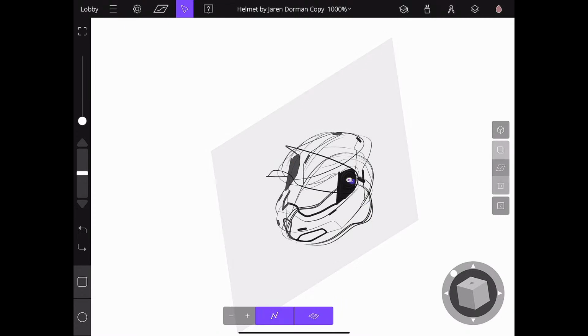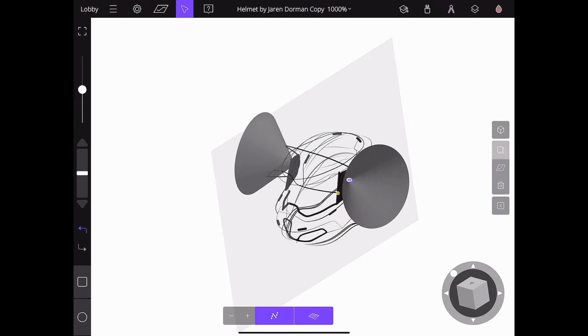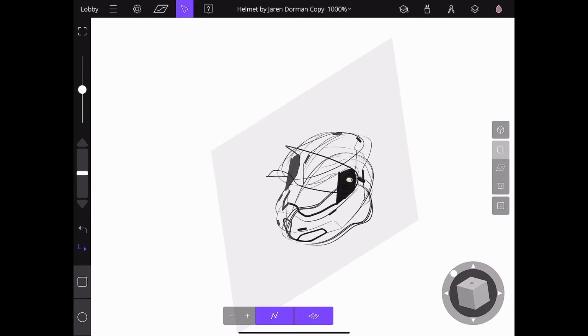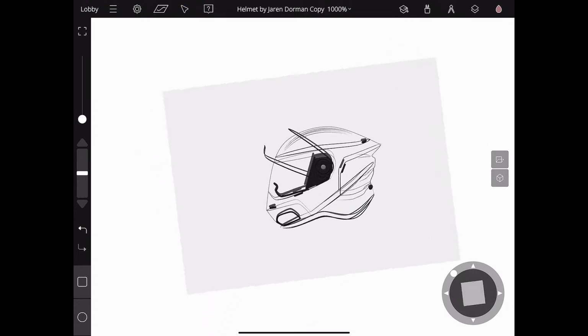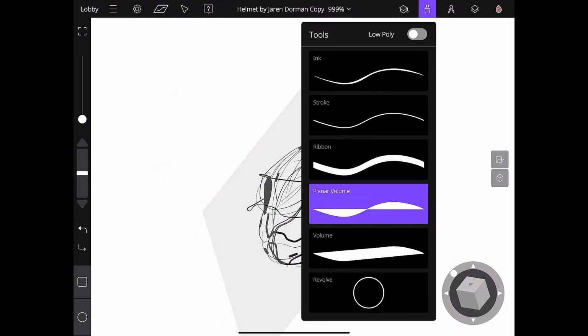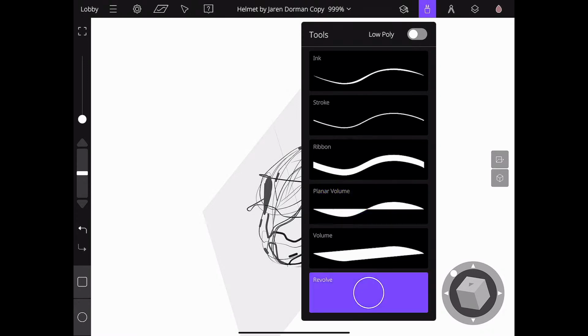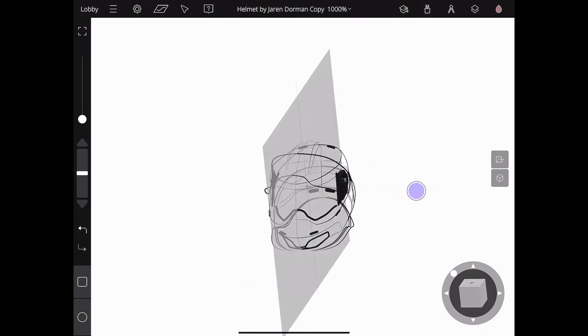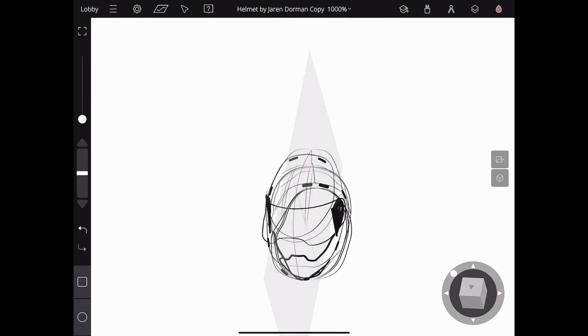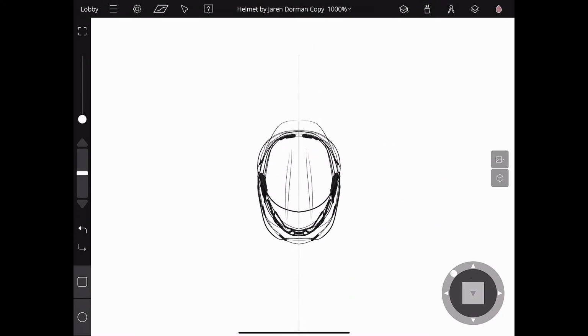If you go into edit mode, you can pull those points out. You can see those are revolved surfaces that have been made. So we can go to this one, and basically how we can do that is, let's see, if we do revolve, yeah, just go down here to the revolve tool, and what we do is go to top view.